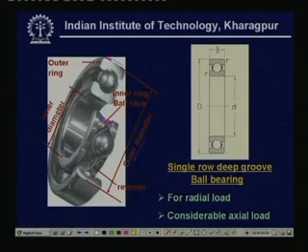Normally in the bearing, the design is made so that the outer ring, having an outside diameter, is placed inside what you call the bearing holder or bearing block, and this is the inner diameter onto which the rotating shaft is assembled. That means you need to make some sort of seat on the shaft. So, the bearing will come and fit over here, so that when the shaft rotates, the inner race rotates and the outer race is always within the bearing housing. This is in the bearing housing, and this is having the rotation.